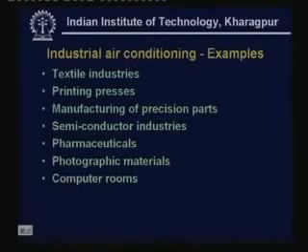And air conditioning is very much required in computer rooms, especially in large computer centers. There is a large amount of heat rejection which has got to be taken out, so you require an air conditioning system. Also, in large computer centers there will be a lot of heat generation because of people, which also needs to be taken out. So all computer centers require good air conditioning systems. They also require clean air, because you should not have any dust particles floating around. So typically you have to maintain not only the temperature and humidity but also the cleanliness of air.